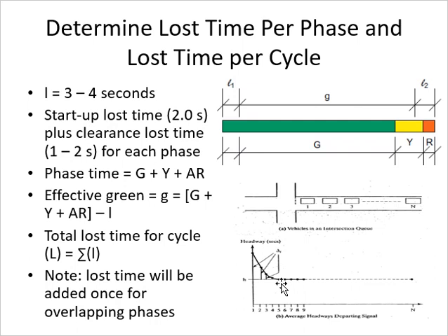Their average headway is considered as normal, because those guys were coming at higher speed, they had more time to prepare, and so on. So if you take the difference between that average value observed after the fourth vehicle and the value for the first 4 vehicles, this difference is called the startup loss time. And they have again given us a recommended value, which is 2 seconds.